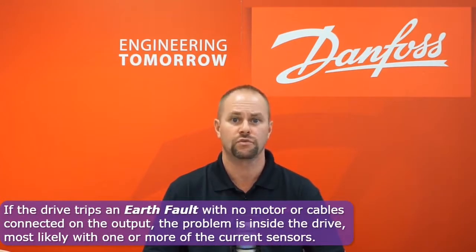If the drive trips again after the restart attempt with no cable or motor connected, it's safe to assume that there's a problem inside the VFD. The likely cause is a bad current sensor. The drive will need to be repaired or replaced. At that point, you'll need to contact a Danfoss tech support specialist for spare part numbers and availability, or to schedule a service visit.